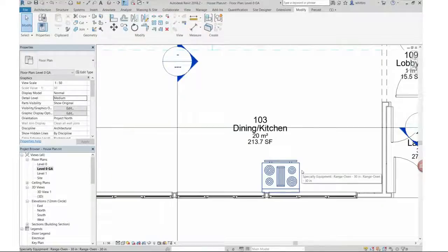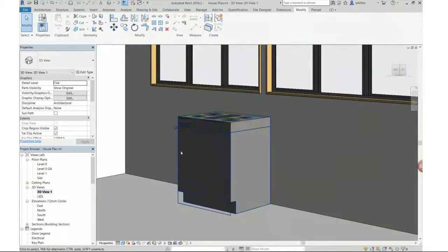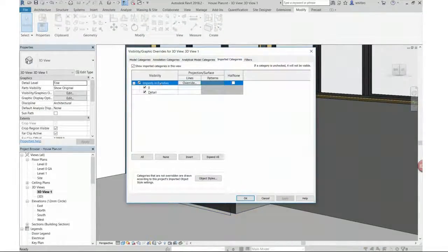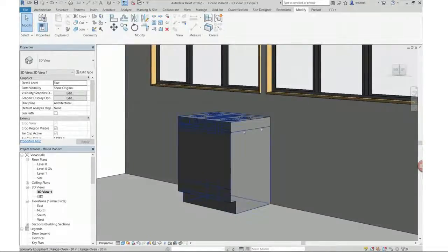I know for a fact that in that DWG the detail of the handles is covered by a layer, so in Revit we can look at the visibility graphics and turn that layer off, because the layer is still visible from the family. That's one of the problems, and having the visibility of that layer is both a good thing and a bad thing. The good thing is you can turn it off. The bad thing is if you don't do that 7Ps bit, you'll end up with as many layers in here as you have in your AutoCAD drawing.